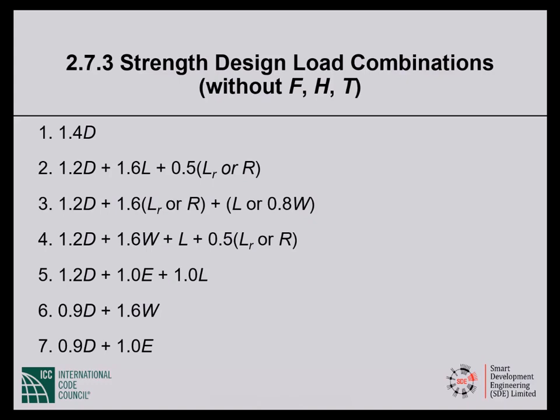Okay. Now, when it comes to seismic design, we have two load combinations, this one and that one. This is the additive seismic load combination. Gravity effects add to seismic effects. Gravity causes negative bending moment at the support section of a beam. Earthquake also causes negative bending moment. If we want to figure out the largest negative bending moment, we use the additive seismic load combination.